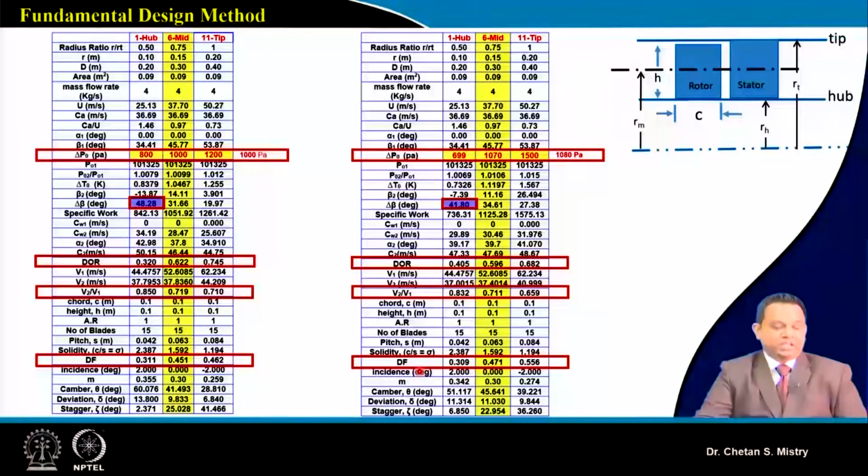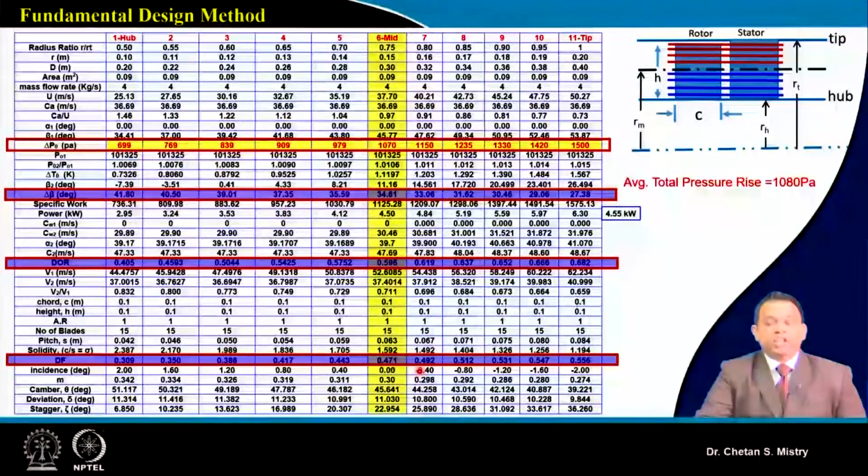So with this, let's divide this into the 11 different stations that we have done. Here, if you look, we have divided it into an equal number of stations, as we have discussed, at an interval of 0.01 meter. And again I am telling you, if you are looking for a more accurate or more precise design, then you need to go with more stations.